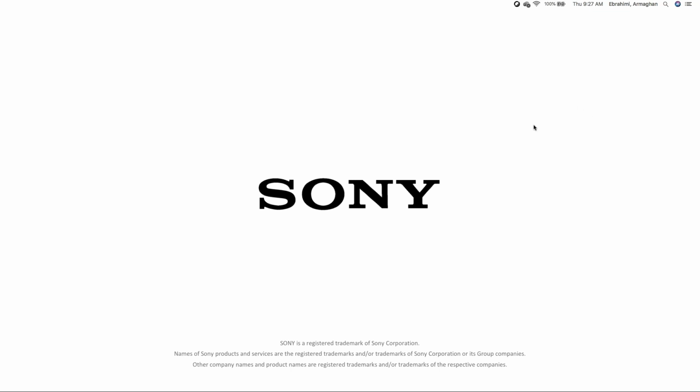Okay. Here's another interesting and good question too. I'm glad that people are putting them into the question section. What is the lowest power consumption in sleep mode? In deep sleep mode, if we modify a little bit of hardware, we can go in deep sleep up to 6 microamperes.